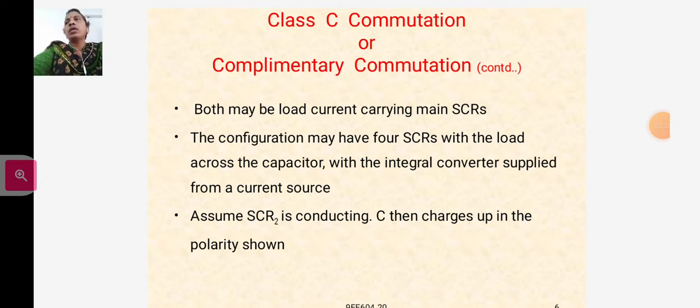In case 1, thyristor T1 is turned on by a gate pulse. Load current flows from the battery to load 1 through thyristor 1, along with a capacitor charging current that flows from the battery through load 2, capacitor C and thyristor T1. This current charges capacitor C to the battery voltage V with polarity. It also has case 2.